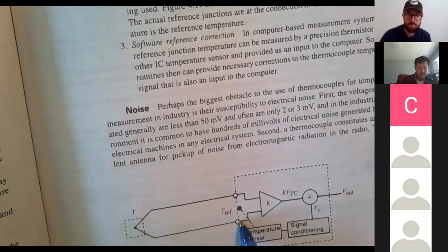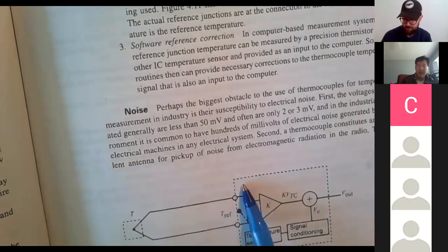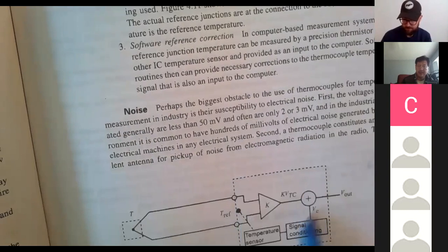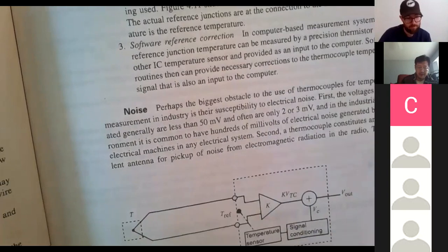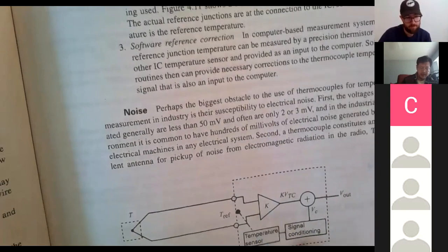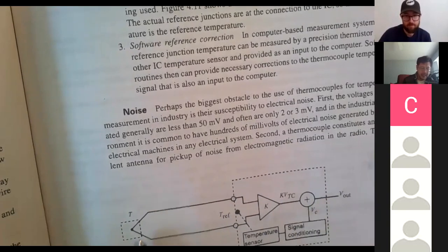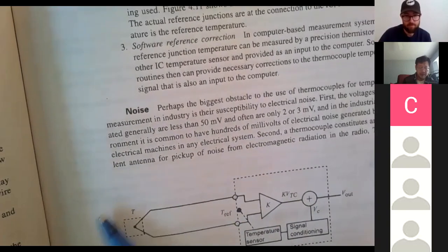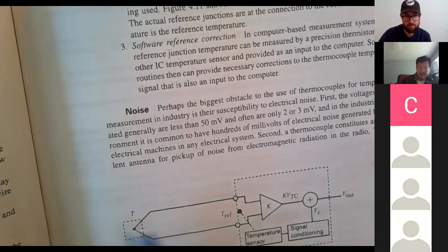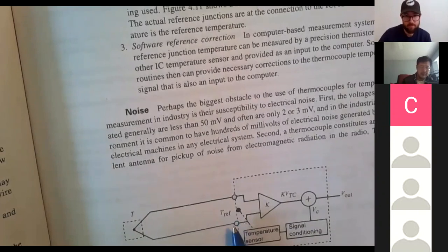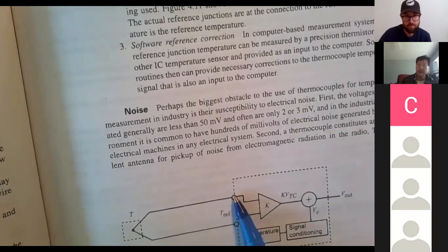That's another thermocouple. And it turned out, if the temperature here is constant, all you change is the reference temperature. We call this temperature here reference. That is your room temperature, because most likely your equipment is at room temperature, and that's your oven. So your oven is 400 degrees. Your oven at 400 degrees didn't change, but the room temperature changed from, for example, in the winter is 30 degrees, in the summer is 100 degrees.